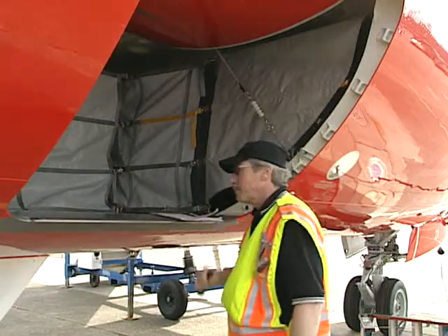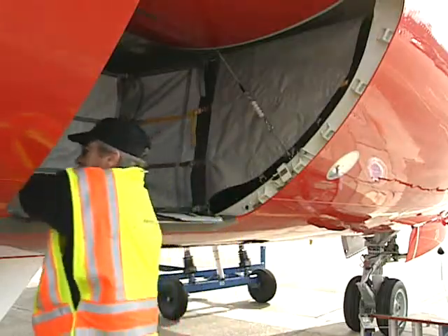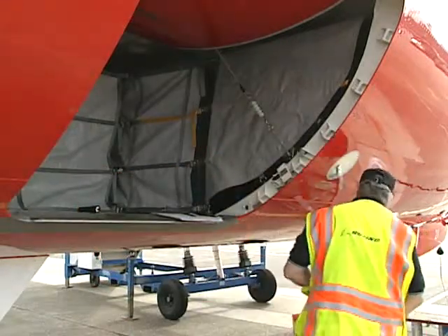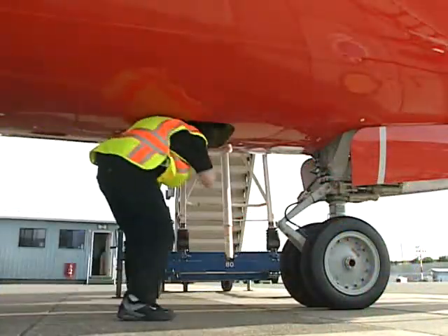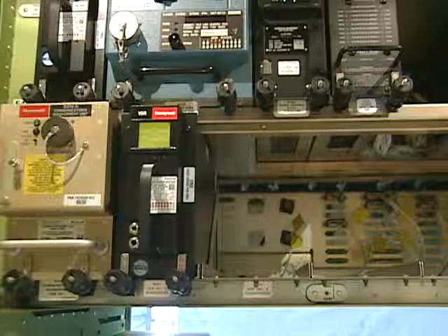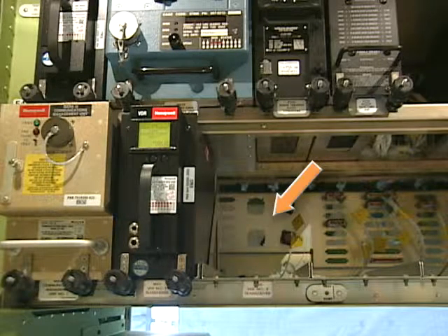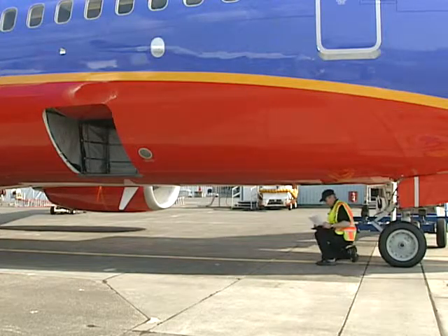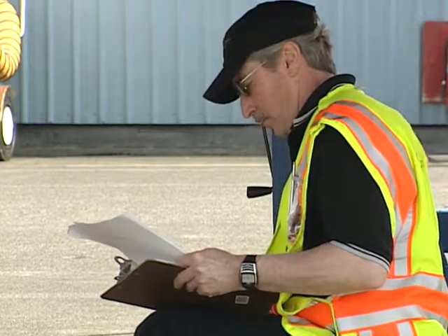Begin the inventory by checking the cargo compartments. Here's an example of something that needs to be removed. Next, check E&E bays. Here's an example of something that's missing. Normally, we would replace a missing item, but this component is out for service and will not be returned prior to weighing, so we need to document its weight and normal location.